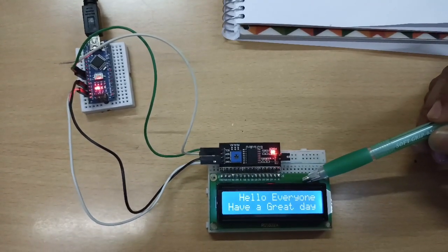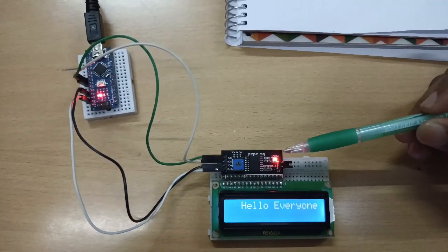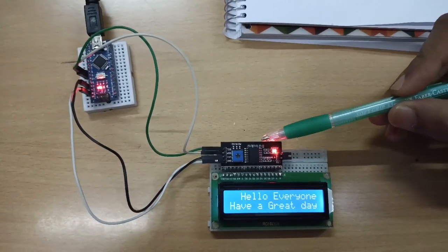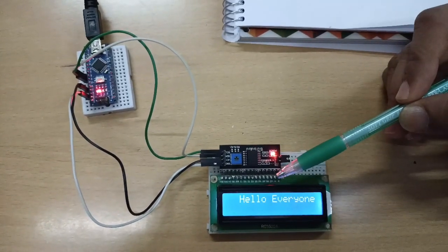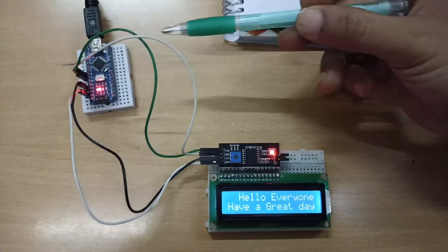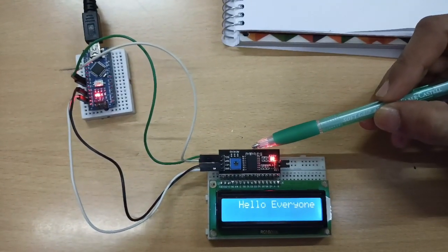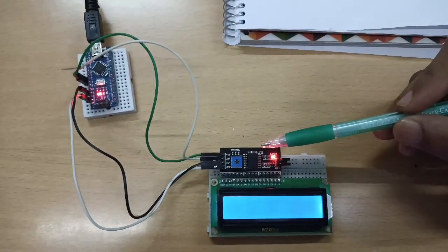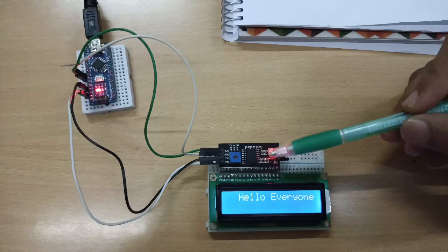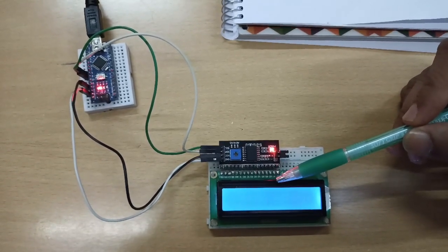where the 16x2 LCD can be connected with the microcontroller only through parallel data transfer because of the presence of PCF8574, which is an I2C to parallel data transfer protocol converter. So the Arduino Nano interconnects with this PCF8574 protocol converter board through I2C protocol. From this board, the LCD interfaces through parallel data transfer as you see in the block diagram here.